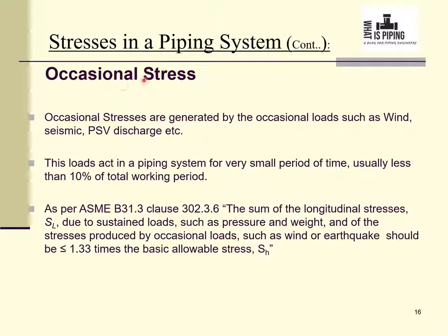Now, what are occasional stresses? Occasional stresses act for a shorter period of time, as per code normally less than 10% of the total working period. Various occasional stresses can be generated in a piping system like wind stresses, seismic stresses, PSV discharge stresses, slug flow, surge flow, etc.